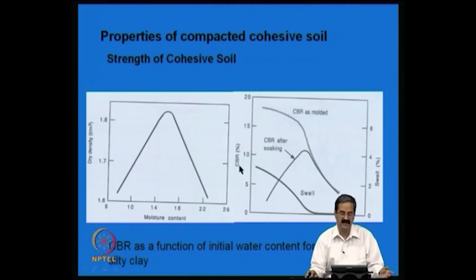CBR is a measure of shear strength of the soil, is it not? The CBR in fact represents the penetration resistance of the subgrade. You should see that the penetration resistance in soaked and unsoaked conditions is close, or if it differs, we should only take the soaked strength in design considerations.